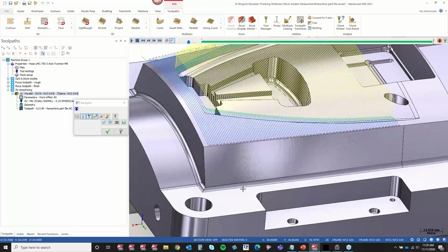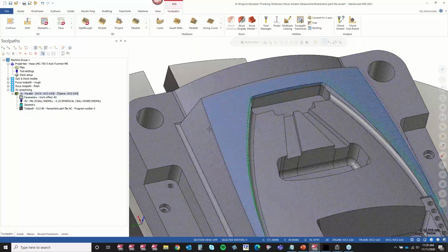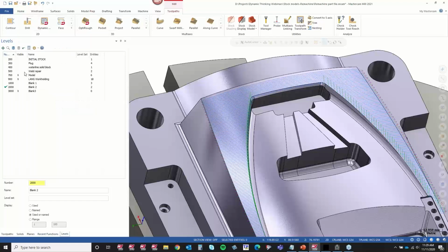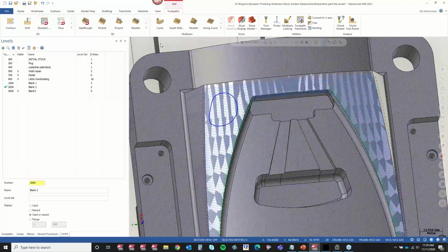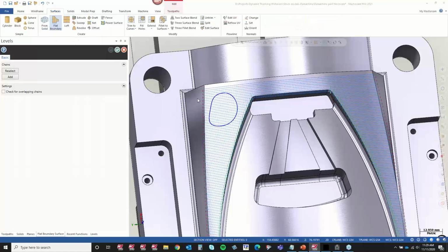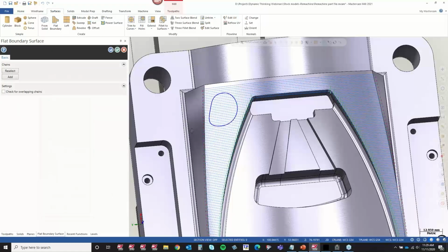We can now, once we get that weld repaired, we're going to leave a big weld bead on this part where that gouge was. We could now trim out this toolpath to show only that area, right? So I'd go in, just draw a quick little boundary about where that is. Now we're going to use that surface to associate the stock model to. I can go back into surfaces, flat boundary, select that boundary.